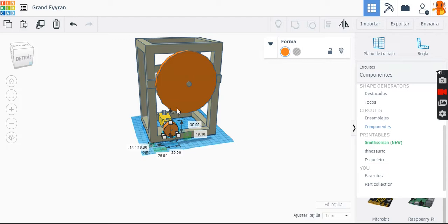The gears are much better to carry the power, but the bad part is that the distance must be very exact for them to be able to mesh. The gears must mesh with each other, and it's very difficult to achieve it if we are not exact.